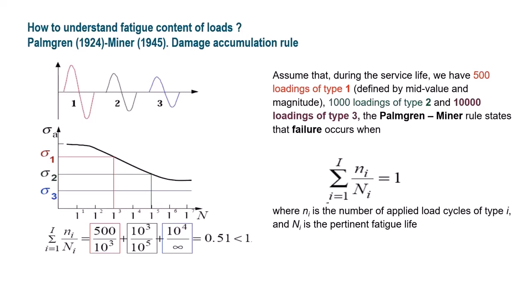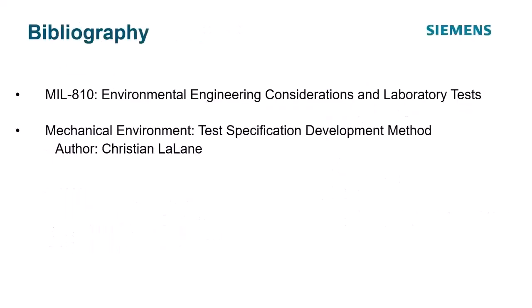So we know what an S-N curve is. That's going to help us calculate damage once we have a stress level. And we know how damage is accumulated. It's a linear model.